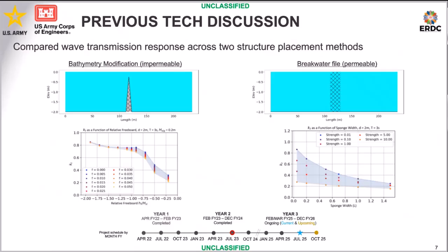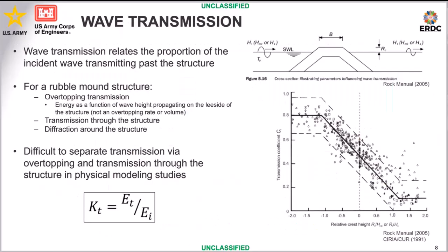And that's kind of what we wanted to investigate a little bit more, using more friction values and comparing wave transmission. This was just wave transmission, so let's add on wave reflection, and also really focus in on the bottom friction and the strength of the sponge layer, the strength of the breakwater permeable layer. So wave transmission, how we're computing these is with internal wave stations.